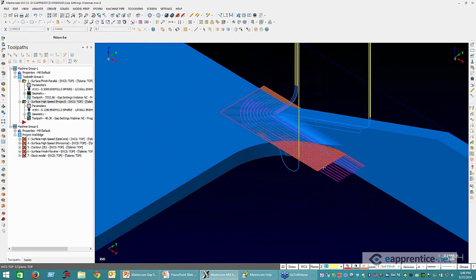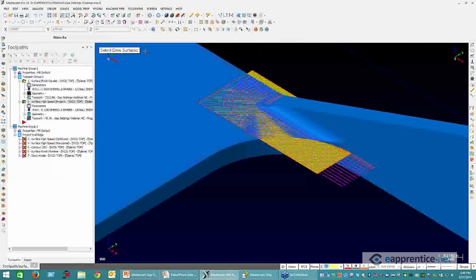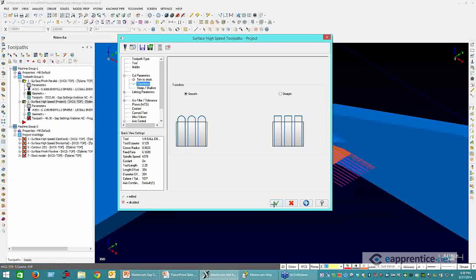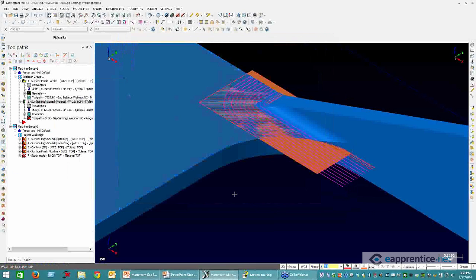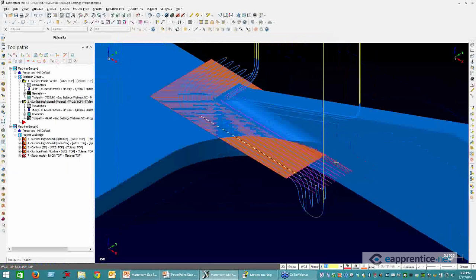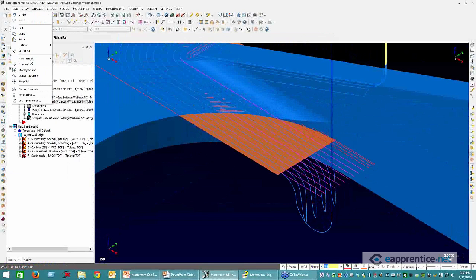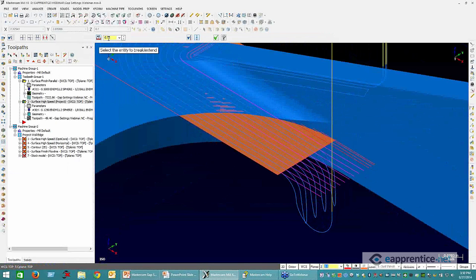Now what I'm going to do is add that surface to my toolpath. And in the parameters, we'll go back to the smooth transition. And that looks a little better. Now the other thing that I can do is shorten up these lines a little bit. So the last thing that I'll do, edit, trim and break, and we'll set this to say minus 0.25, and we'll set that mode to trim.